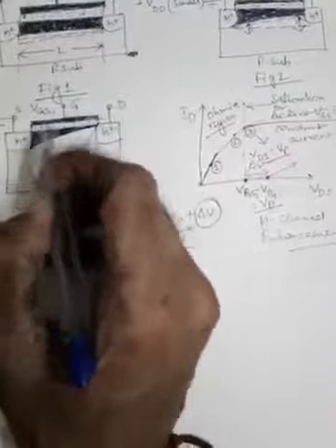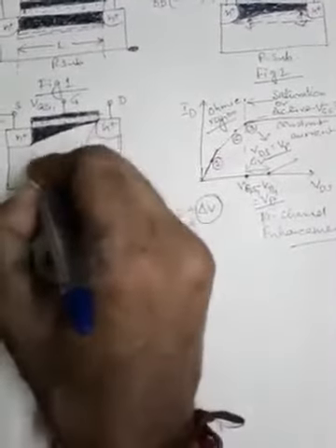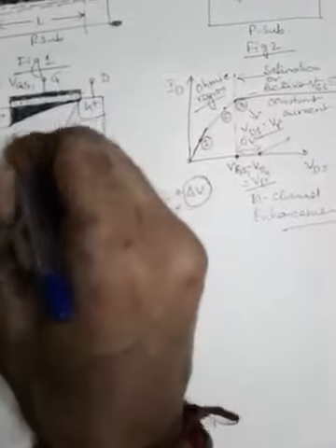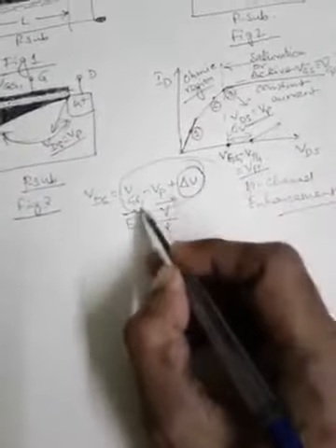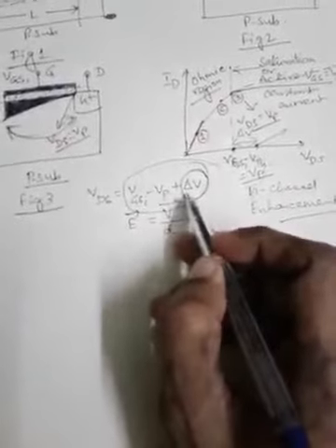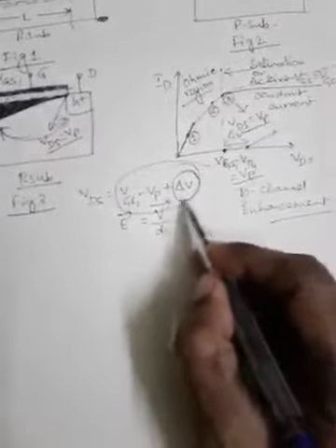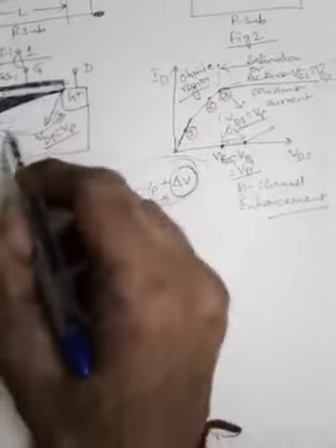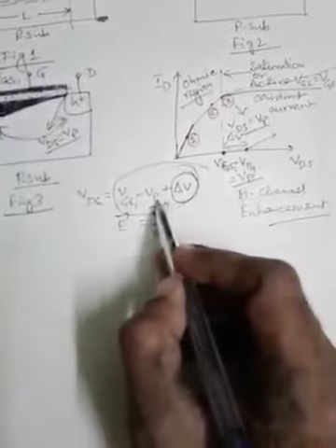Now, within this channel, this whole voltage is appearing. So the electric field is between these two terminals, source and drain, and since it is proportional to the voltage, we can say the electric field is proportional to VGS1 minus VP plus delta V. But initially, when this delta V was not there, it was just proportional to VGS1 minus VP.